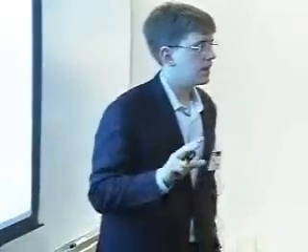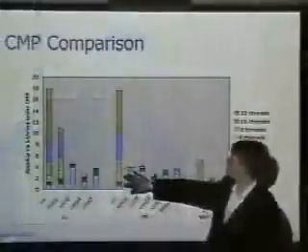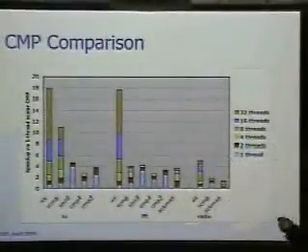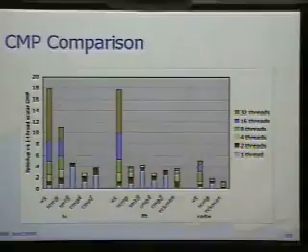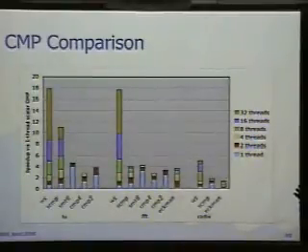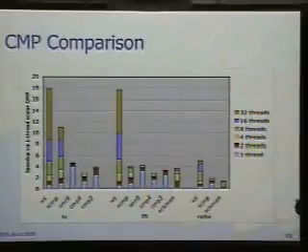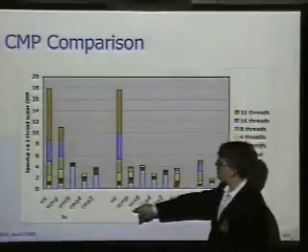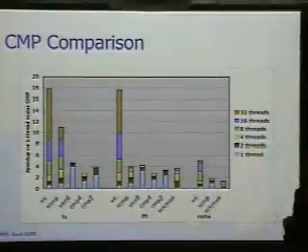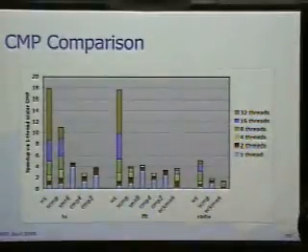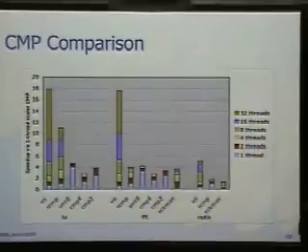Turns out there are 2 things that account for the performance gap between SCMP and the WaveScalar processor. The first is that SCMP uses a broadcast bus for coherence traffic and memory traffic, and as more cores are added to that bus, it becomes saturated. The second thing that's going on is that in particular for FFT, the threads are relatively small, and so WaveScalar is actually able to pack more than one thread into a single cluster. And that means that when those threads communicate, they do so through the shared L1 data cache, so that communication is very, very cheap. So it's a combination of those 2 factors that account for that gap.